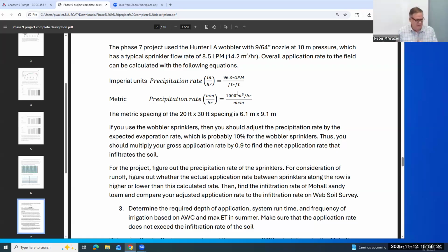The reason I'm recommending it is we have such evaporation problems in Arizona with sprinklers. This has large drops. But I wouldn't actually put one in without seeing it in other people's farms and seeing that it works. For example, maybe insects get in it. Maybe bees lay eggs in it. There's just so many things you can't plan on. Maybe the water is corrosive towards this sprinkler. Probably not, because it's plastic. Maybe there's sand in the water that degrades it.